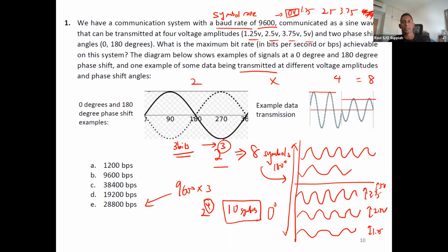So if you use more bits than needed, you are wasting your bandwidth. For example here, instead of 3 bits for each symbol, you use 4 bits. It can still work, but then you are transmitting a 4th bit that is not going to carry any additional information. Your system will still work, because you transmit 4 bits and receive 4 bits, but you are transmitting an additional bit that does not carry any valuable information. So it's a waste of your bandwidth.